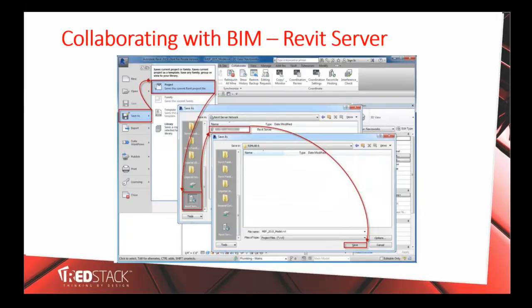The end user would save the central file using Save As, then select your project, and in the places area, or on the place list of the Save As, instead of selecting a folder name, you select Revit Server. You then browse directly to your Revit Server host, and then eventually you save the project as, and away you go.